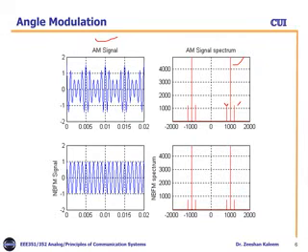So similarly, for narrowband FM, we plotted a spectrum, and you can see that the modulated signal here is different in time domain, but in frequency domain, if you notice, they are exactly similar. With different phase, because here no phase is plotted, this is only the amplitude. So in amplitude they are similar, maybe with some values a little bit less or more, but at the same points they have fc plus fm and fc minus fm, so only 2B bandwidth, but their phase will be different.